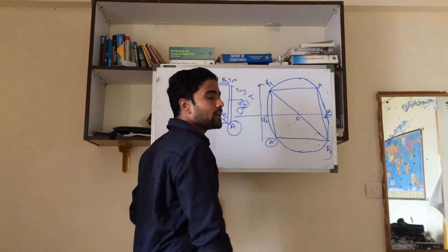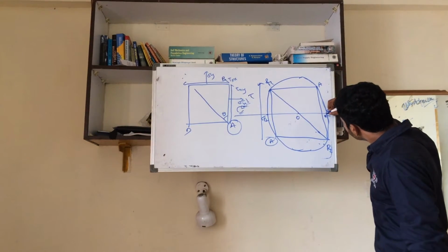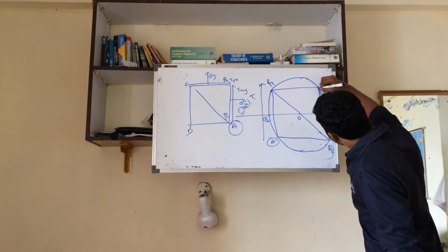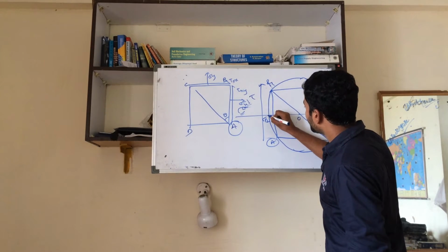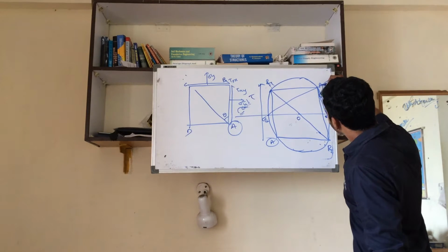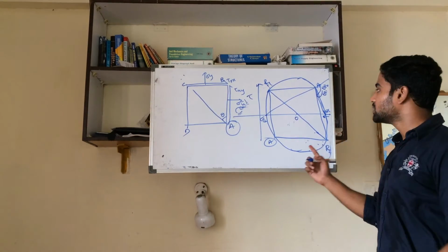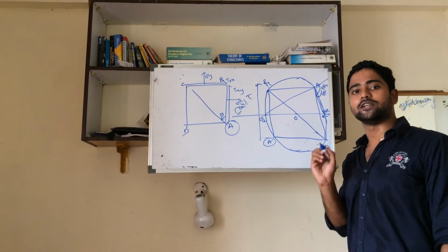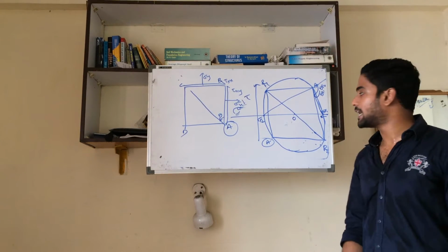And if you want to calculate the maximum principal plane theta p, just join these two points with a straight line and measure the angle with the protractor. That would be theta p1. And if you want to calculate theta p2, this is how you will calculate this one as theta p2. And remember, here theta anti-clockwise is taken as positive. If it is clockwise, it will be taken as negative. So this is how theta p1 and theta p2 are calculated.